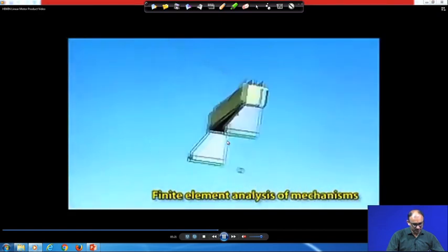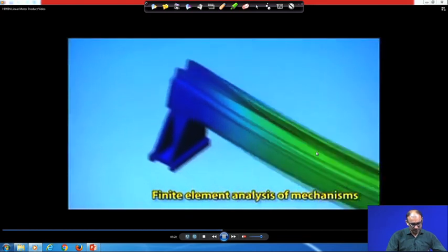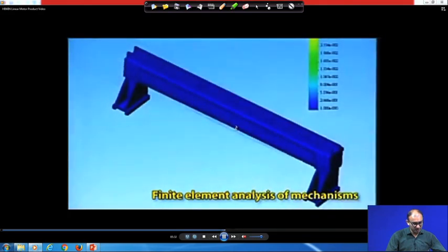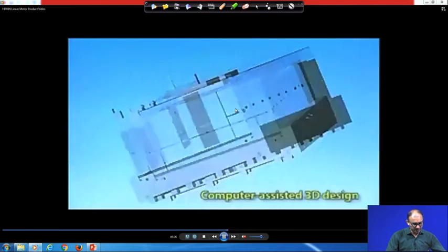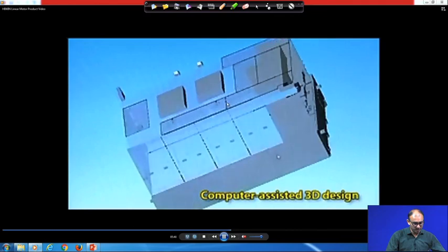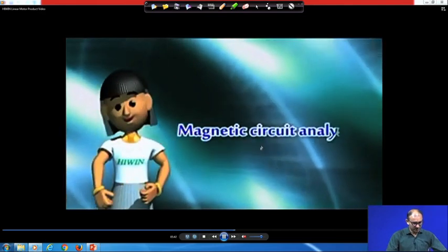All these things can be analyzed by finite element analysis. You can also do frequency mode analysis, to see how much bending of the rail there is when it is under motion. If you are supplying current, what is the heating of the whole component, and is the heat concentrated anywhere? These things can be analyzed by such software.